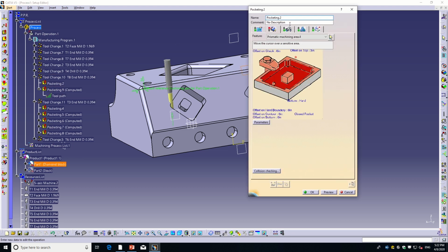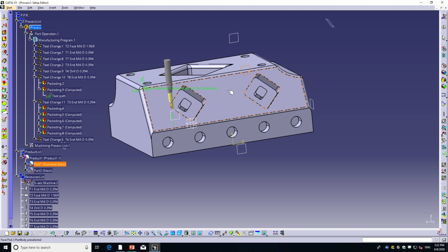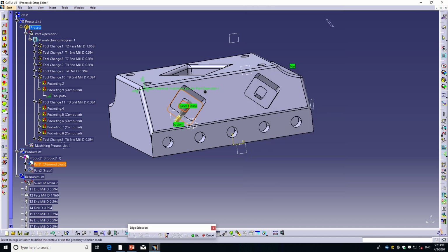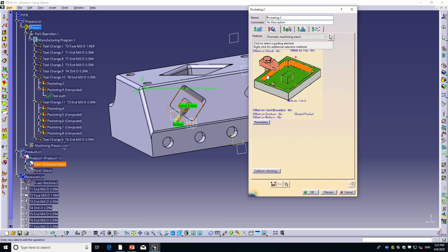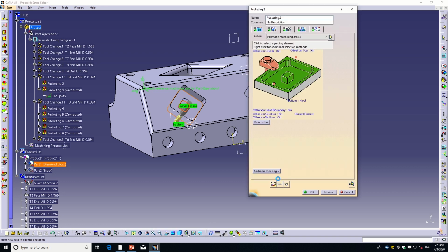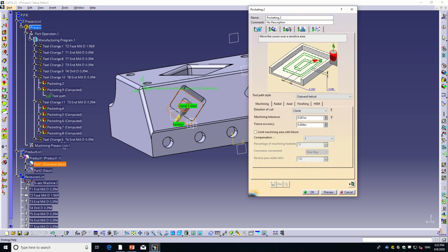Select the slanted side for the top plane and the bottom surface inside the diamond for the bottom plane. Right-click on the drive and remove all contours. Right-click again on the drive and select by boundary of faces, and click on the inside of the diamond. Make sure it is a closed pocket and keep all the islands.